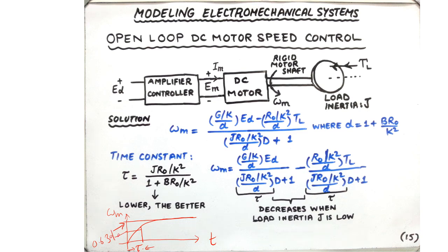So how do we find the expression for the time constant? Well, we just look at the denominator and identify the coefficient of the differential operator d. So the time constant is nothing but JR0 over K, this guy over here. You might be wondering that this is a first order system, but in terms of two inputs. So you can write this as the weighted sum of two first order system transfer functions, but in both cases the coefficient of the d is the same.